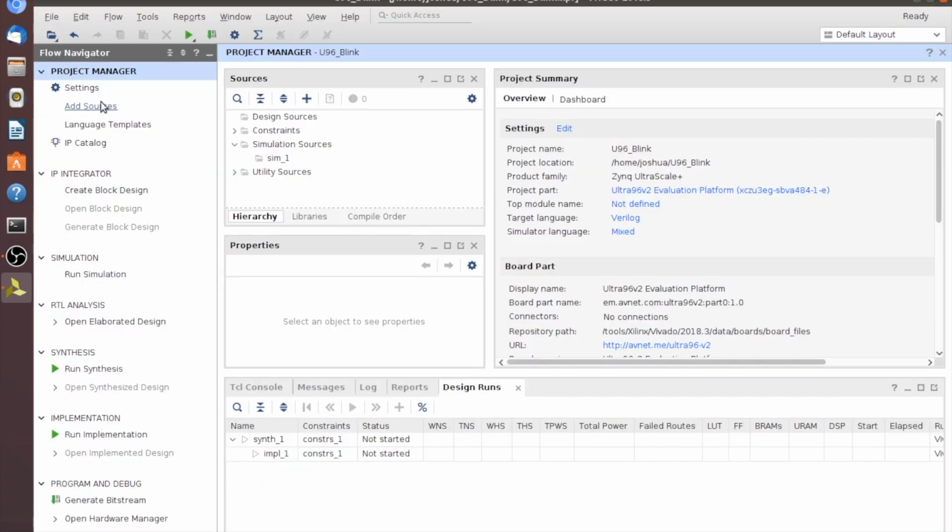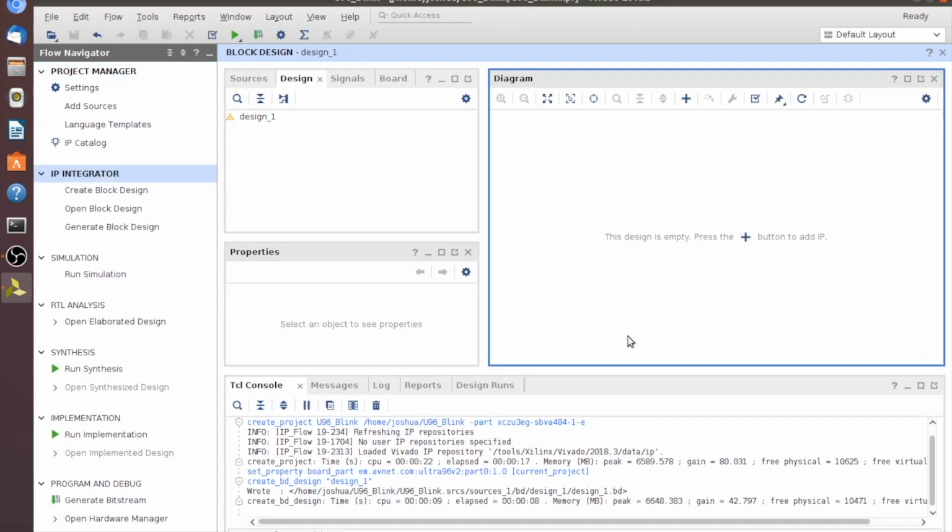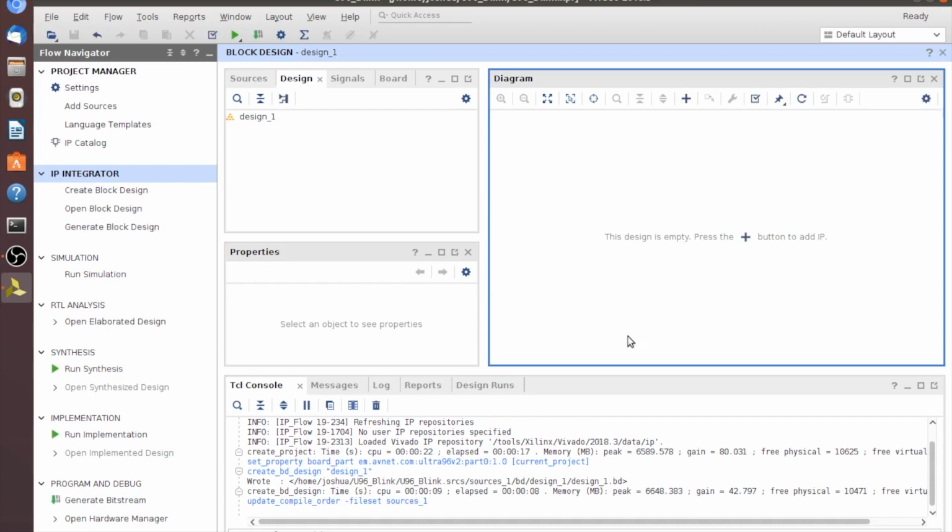So what I'm actually going to do with this is follow the base project design for the very start. Unfortunately, the way this is designed, there isn't a real immediate clock into the PL, so we're going to have to use the PS as PL. So if you want to know how to do the base design, see the previous video, and I'll link that down below as well.